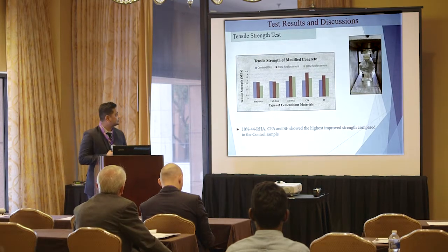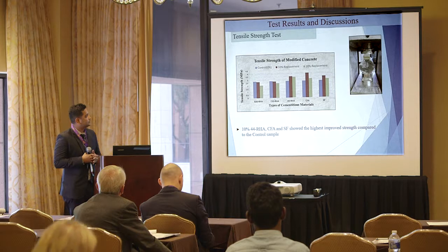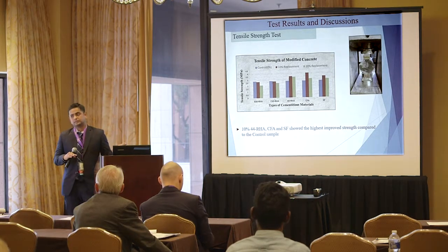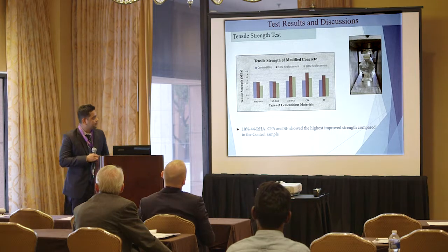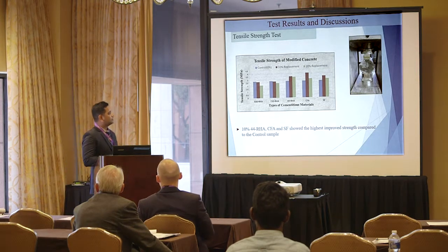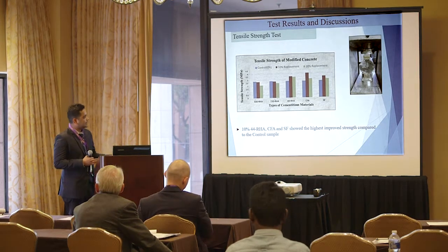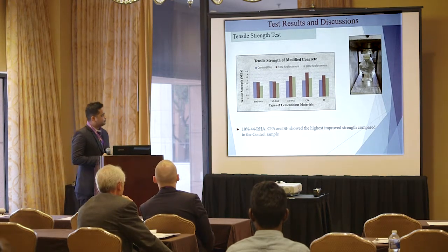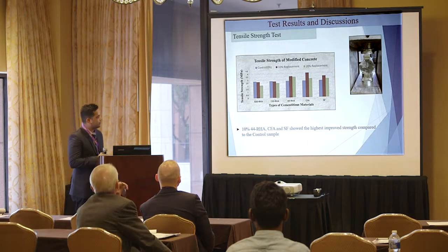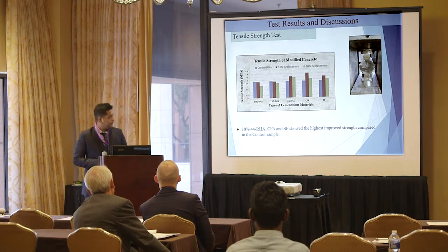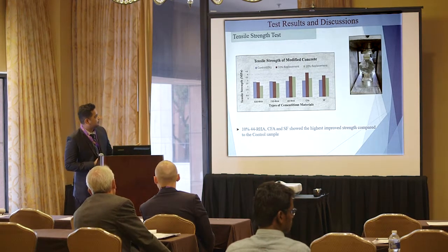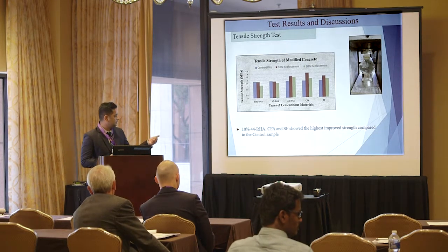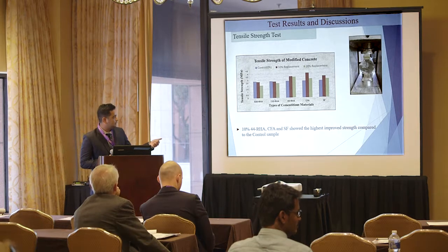And this is the tensile strength test which I did, and it also followed a similar trend to the compressive strength test. Here also the finest RHA shows the highest result, followed by the CFA and the silica fume as well. And also the 10% replacement gives the optimum result here.